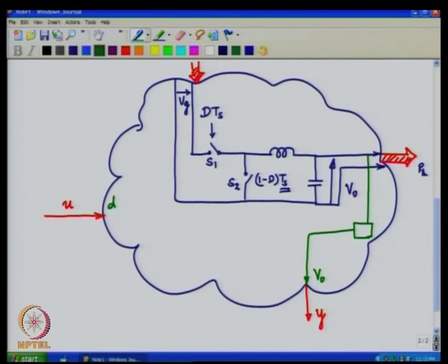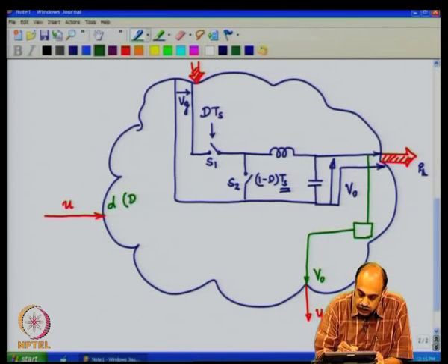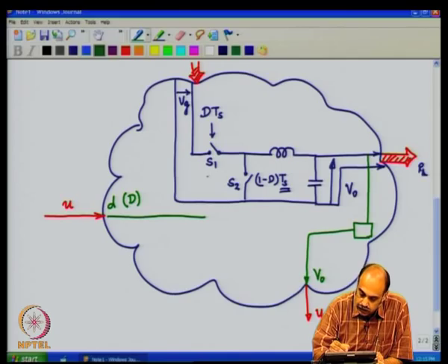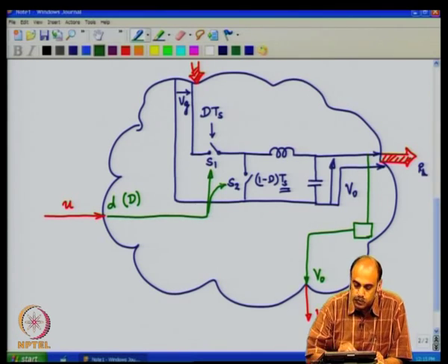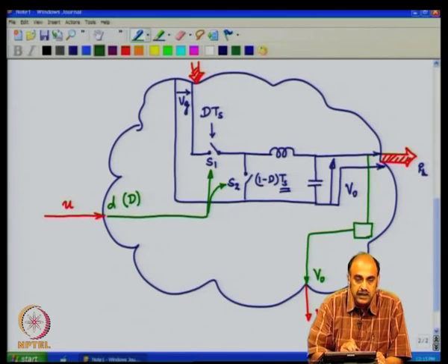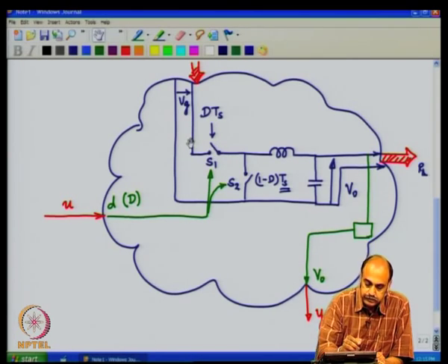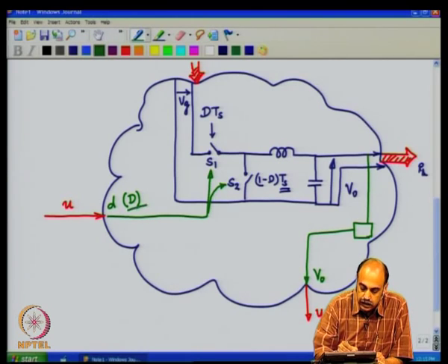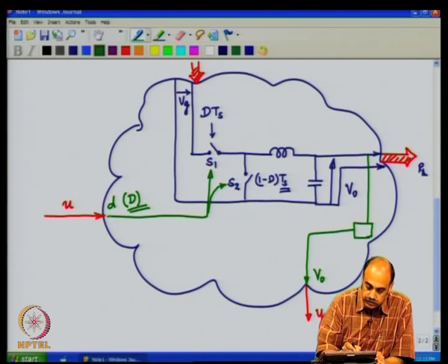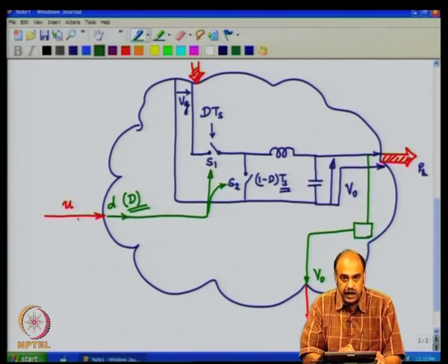D. In the steady state, we say it is uppercase D. So, this D implies that you are in some manner trying to adjust the times for which these two switches are on and off. So, in effect it is actually one control input, because these two switches are directly coupled. They have only a single variable D to control them, and they are mutually exclusive. So, in effect we have one control variable D, and that is what is brought out as the plant control input.